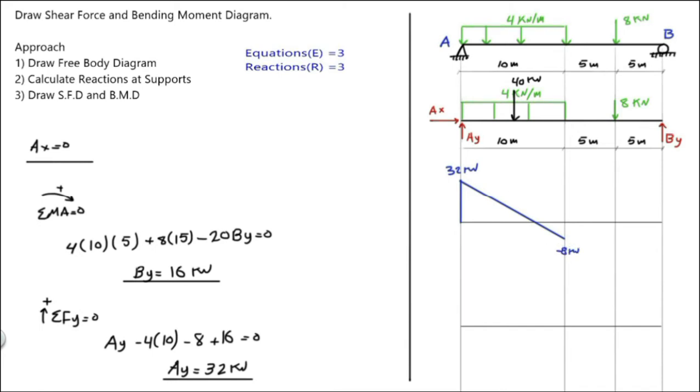Now nothing is changing here. So we go the zero slope. Here there is minus 8. So we go minus 8, which is minus 16. And here nothing is changing. Go straight line. Here we have the amount of By, which is 16. Don't forget to put the values.